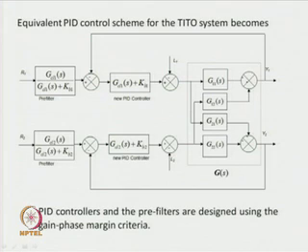Now, G(s) represents the 2 input 2 output process, which is now subjected to a new PID controller, where the parallel PID controller is added with the proportional controller KB1, and for the second loop the new PID controller has the proportional controller KB2.